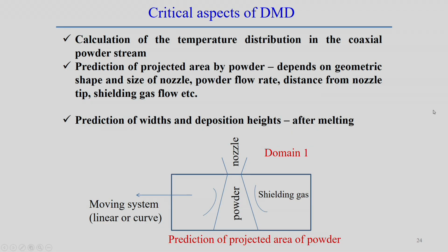By looking at that kind of beam profile, we can optimize the laser scanning speed, and of course the powder feed rate, the shielding gas flow, and other parameters as well. So, we look at the typical aspects we have to consider for the development of the direct metal deposition technique, and I am mentioning the typical areas where we need to focus.